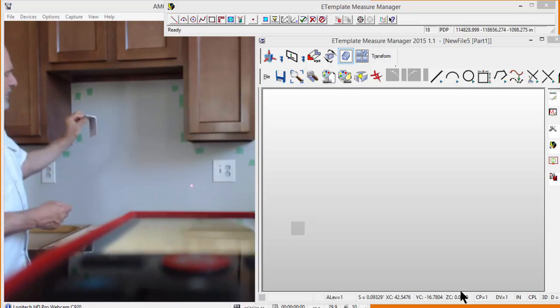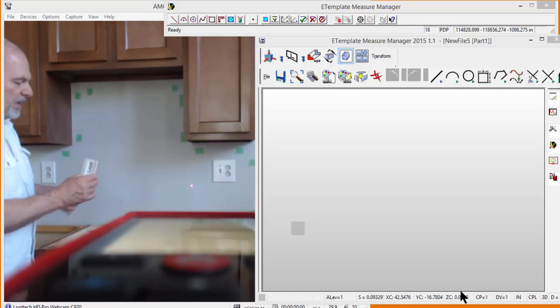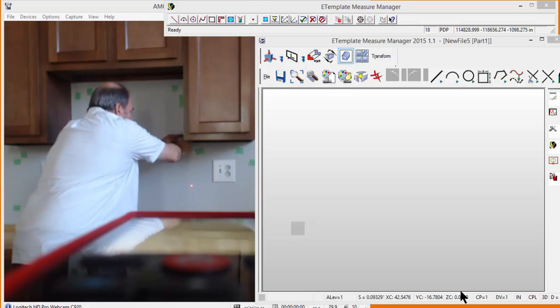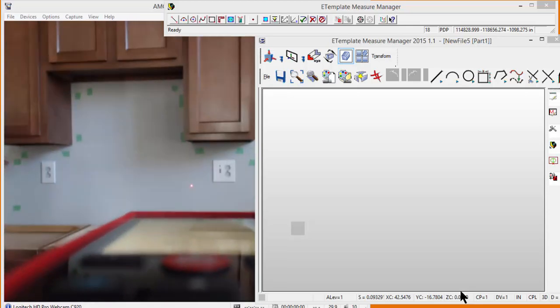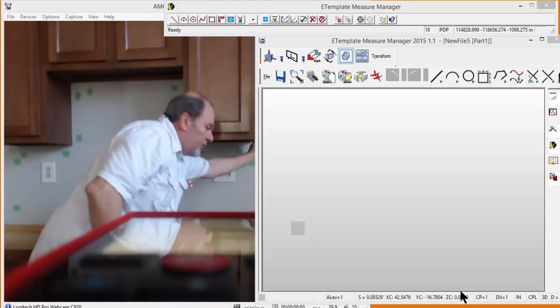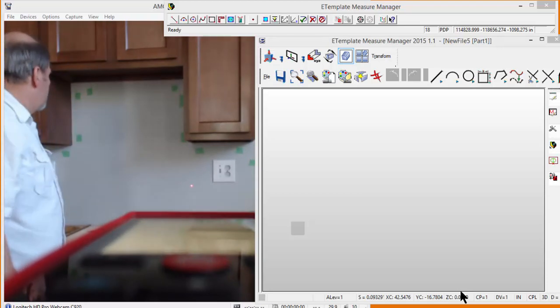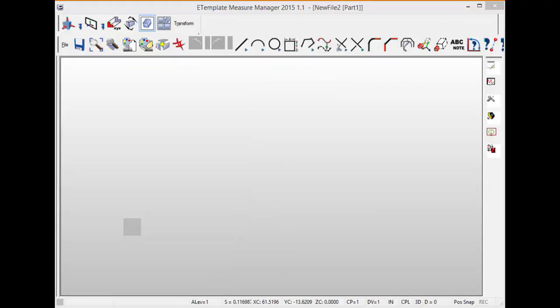So what we do instead is we take this as part of your template markers, and this is exactly 2 inches. So we put tape around, and we mark 2 inches offset all along the perimeter. This is marked down directly from the wall, from this side here. And the same thing here. This is marked directly down from here using a 6-foot level. So that gives us a complete outline of the template that we're going to use for backsplash.